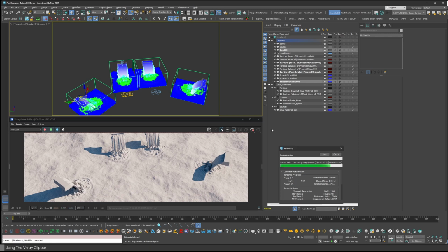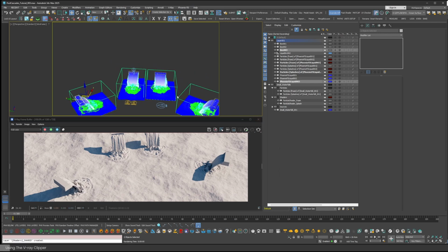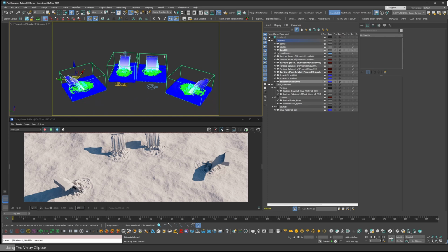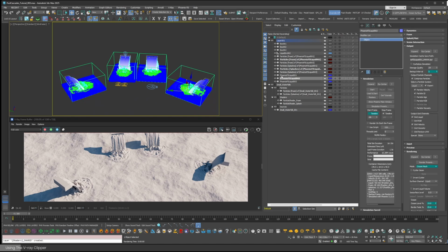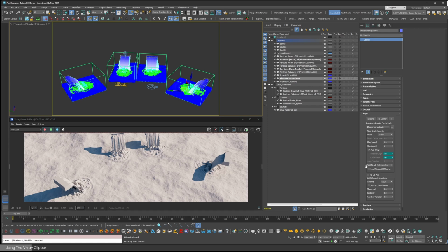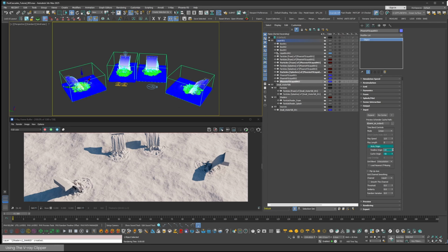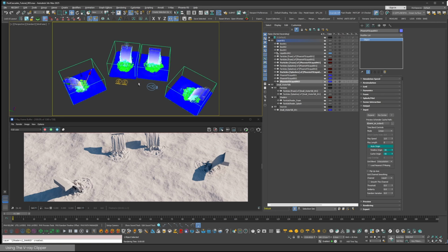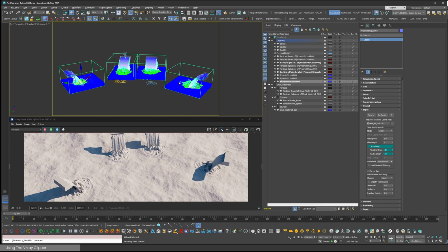And of course, currently I have the original simulation and I made another slightly different one. But then I have two more copies that are exactly the same. Not that you can tell looking at them from a different angle, but still. You can randomize the starting position on the timeline. That's another reason why I calculated this 50-frame pre-roll. I can go into the input rollout, uncheck the auto origin, and randomize the starting frame. Pick another random timeline origin for the other copy. And now, the fact that they are the same will be even harder to notice. You can get away with a single simulation like I did in my original scene.